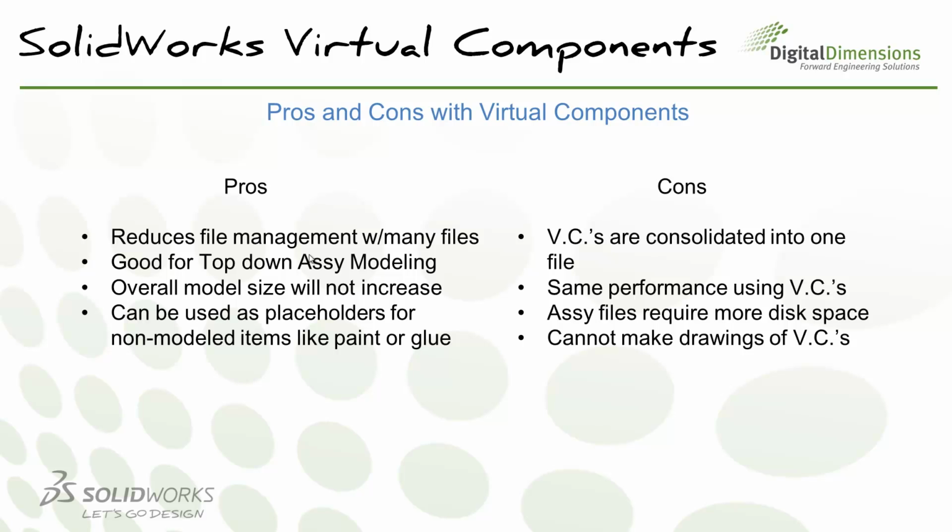Now another con, I guess I can put it into the con section, is this is actually a common question I get. If I create components as virtual components, will I still see the same performance? Will I actually see faster performance with regards to rebuilds, because it doesn't have to find all these references? After some research, I don't see a change in performance with regards to SolidWorks when you're working with regular components versus virtual components.